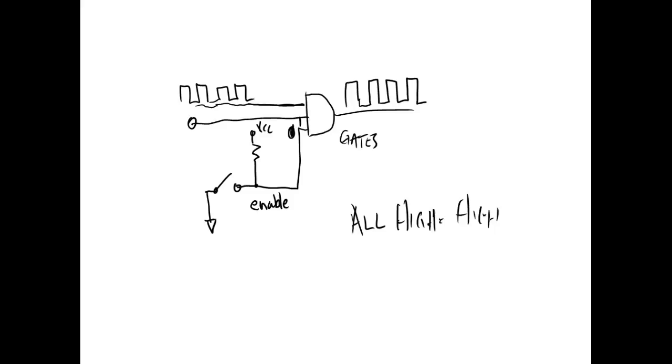Enable. So we have a special circuit called address decoders. It's inside the chipset now, and it looks for addresses. And when the address for this device comes out, it'll enable one device and everybody else is what? Disabled. Kind of like the mailman or the mail person coming up to your mailbox. So they usually only get into one mailbox at a time, right? You understand that? And that's basically how address decoders work. Okay, so this would be an AND enable.